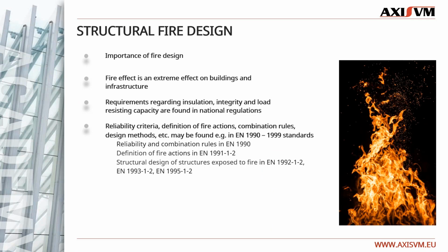About structural fire design and fire design of buildings. Fire design of buildings is a very important issue of building safety. The consequences of a possible fire are severe, and the nature of fire is highly nonlinear, and structural response given a possible fire is also highly nonlinear. So we have to ensure the reliability of the structural elements against a possible failure in a fire. Requirements regarding insulation, integrity, and load-resisting capacity may be found in national fire safety regulations.